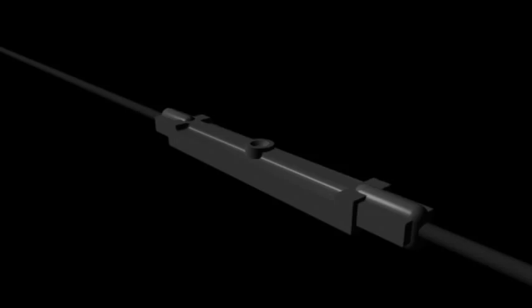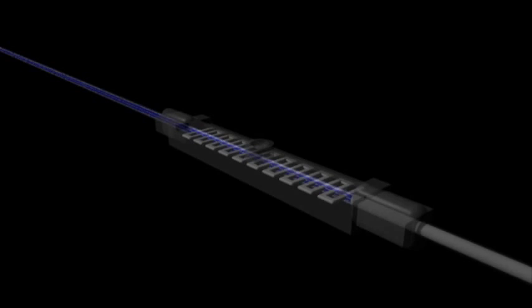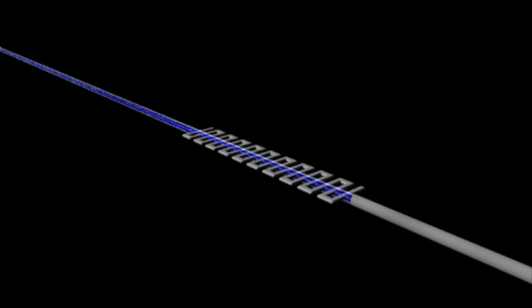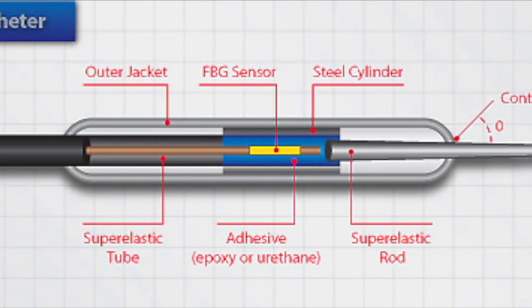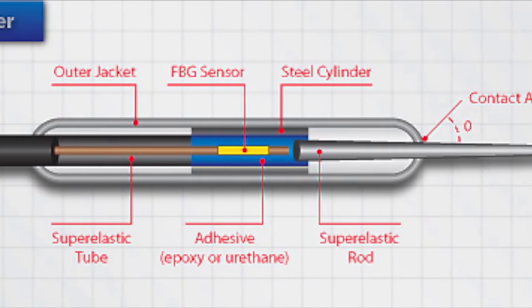This is the strain sensor. It is comprised of a fiber Bragg grating. It is glued to the material being measured. Stretching and compression of the strain sensor changes the fiber Bragg grating spacing, and the wavelength reflected changes. In the thermal sensor, the index of refraction changes with temperature, and the wavelength shifts.